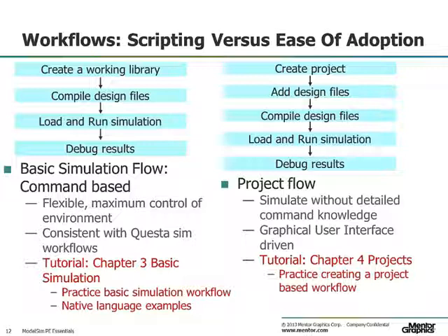Now the project flow allows you to come up to speed without having detailed command line knowledge. It's driven through the graphical user interface. Chapter 4 introduces projects and allows you to use the Verilog or VHDL workflows so you can practice in your own native language. Some of the things that the project workflow does for you is it simplifies the interaction with ModelSim. You don't need to know the intricacies of the compiler switches and library mappings.